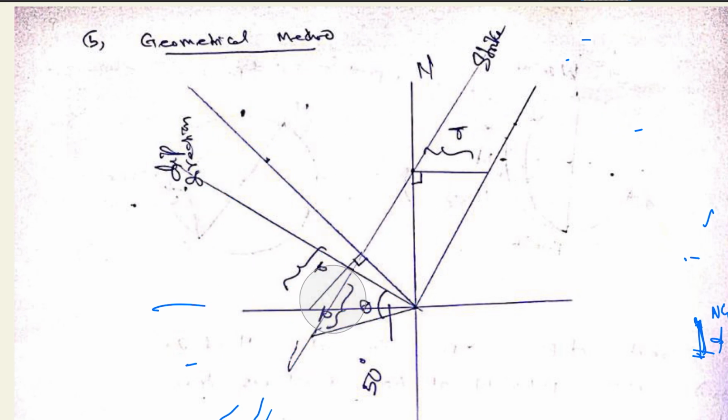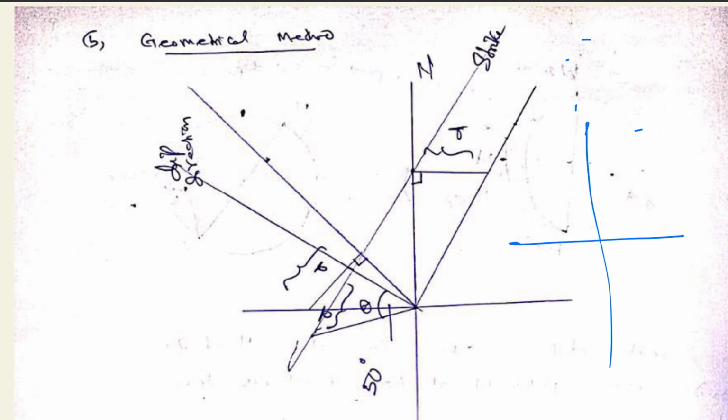Let me discuss it again so that it will be clear. First we draw along north, the angle is 30 degree. At any point you draw just perpendicular, so to know the spacing d. Then along north 45 degree west line, this is the apparent dip direction. Along this we have the dip amount of 45 degree drawn. So to this line we have to find out the d spacing where it will touch this line.